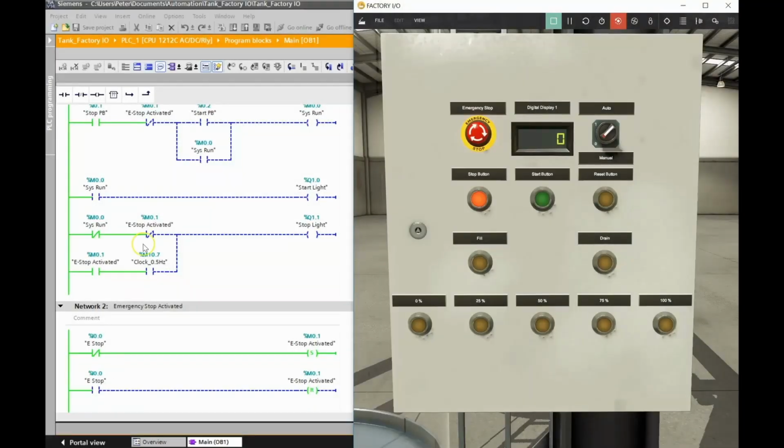So in this video, we're going to keep going, and we're going to make use of the auto manual switch. So we're going to make use of this guy right here. And we're also going to make use of the reset push button. And those will be all our different settings for our control panel that will then control other things in the program. And we can use those as base instructions on any projects that come up, right? So we've had the stop, the start, the e-stop, then auto manual, and then the reset. All right, let's jump right into it.